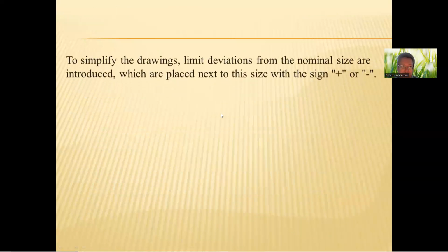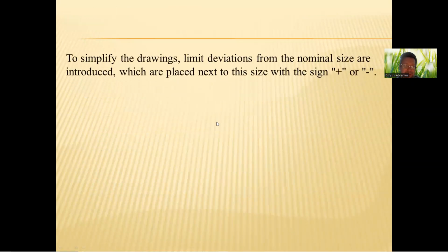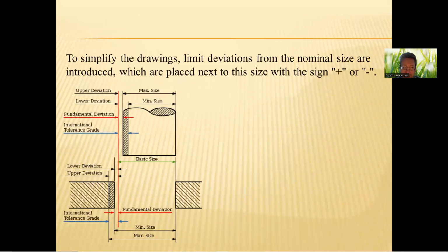And next slide. To simplify the drawings, limit deviations from the nominal size are introduced, which are placed next to this size with the sign plus or minus.